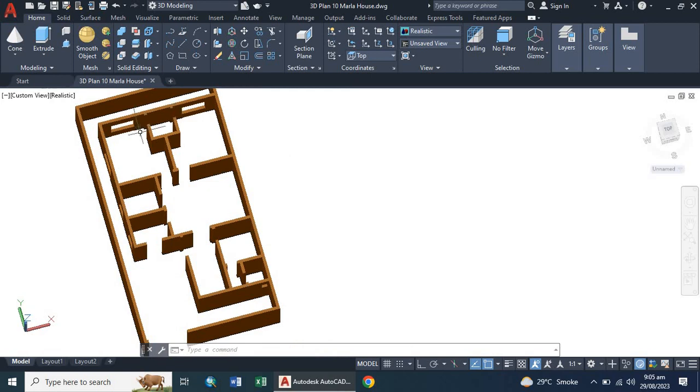So in the case of doors, the recommended size of door is 7 feet. So the door starts from the ground level. We have to provide the level above, which is above lintel, so we don't have to provide our sill level here. In case of doors, the total height of the wall is 11 feet. We will provide a 7 feet door, and the upper side we will provide 4 feet level above the lintel.